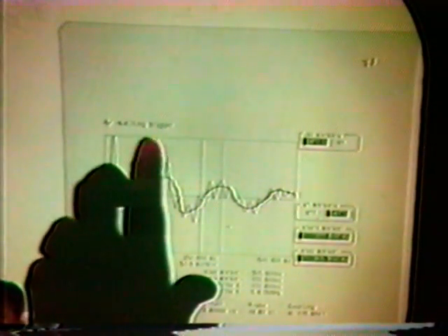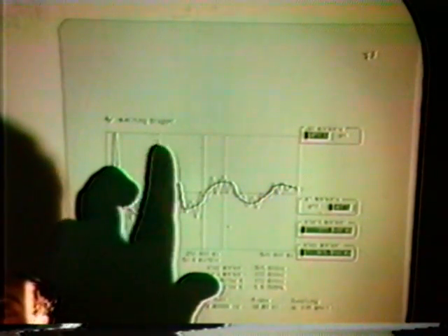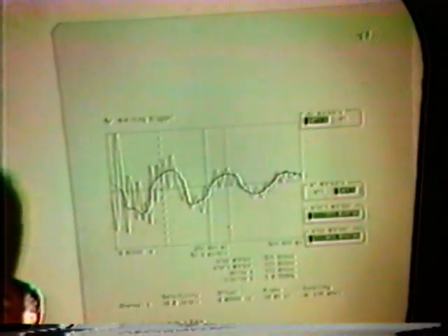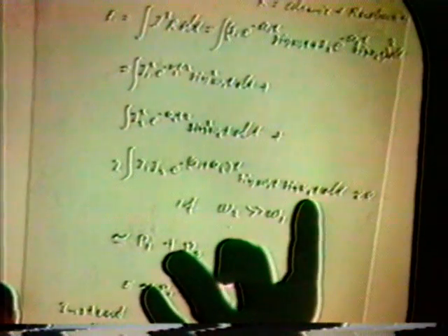Now the integral containing the double product is practically zero, for the following reason. If one frequency is much bigger than the other, we can see, if we split the integral into sections, that the high frequency reverses sign symmetrically while the other factor remains constant here. The other one reverses plus and minus, so in the integration it should be almost zero. Something practically residual will remain, but over a long time this will sum up to zero.